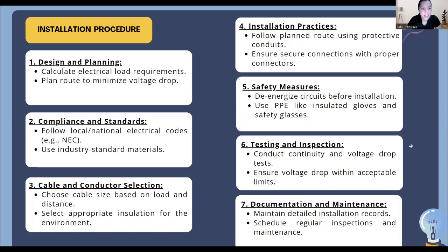The next is safety measures: de-energize circuits before installation and use PPE. Testing and inspection: conduct continuity and voltage drop tests to ensure proper connections and acceptable voltage drop levels. Documentation and maintenance: maintain detailed records and schedule regular inspection and maintenance for reliability.